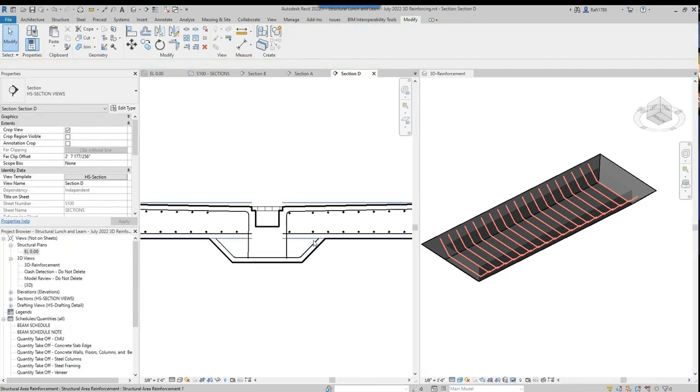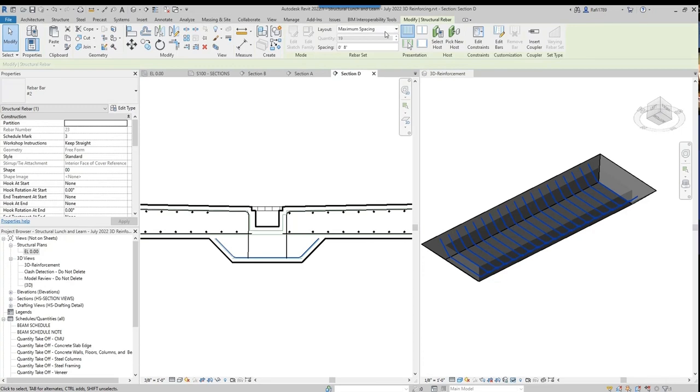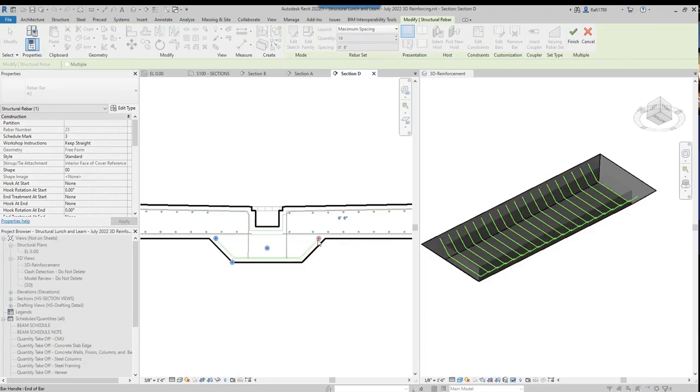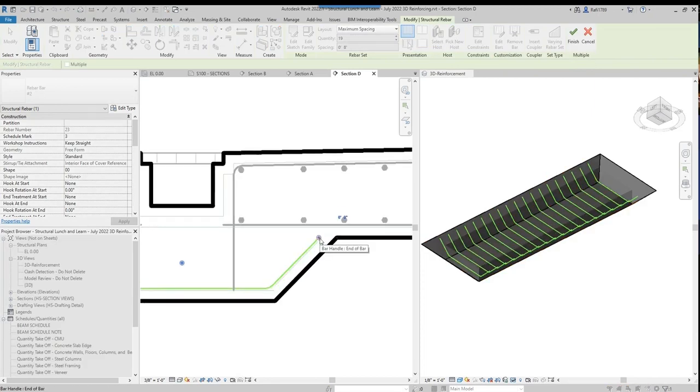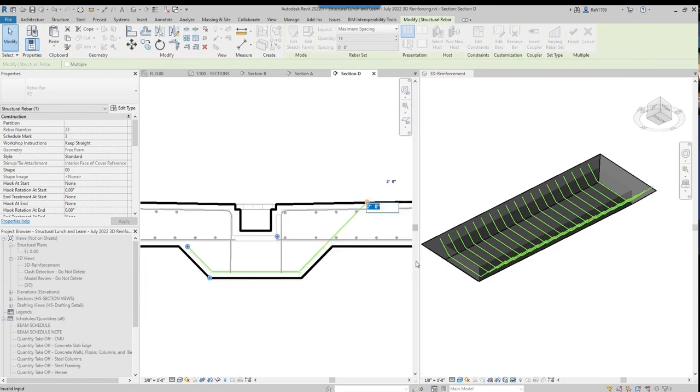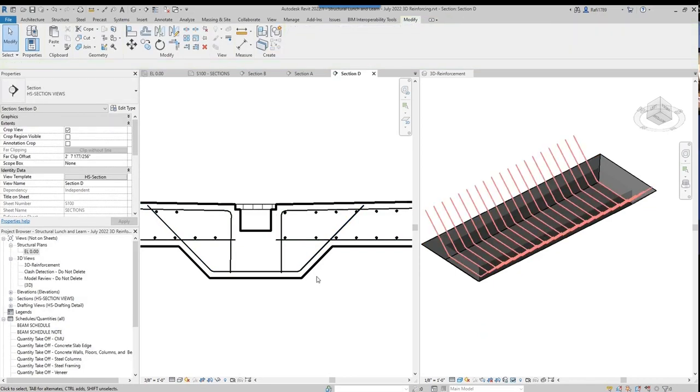In here, or wherever really, I can edit my constraints, and I can click on this end constraint and just extend it. I did 2 feet, that's a little bit too long. 1 foot 10, beautiful. So I'll do 1 foot 10 on this side. And there's my shape.